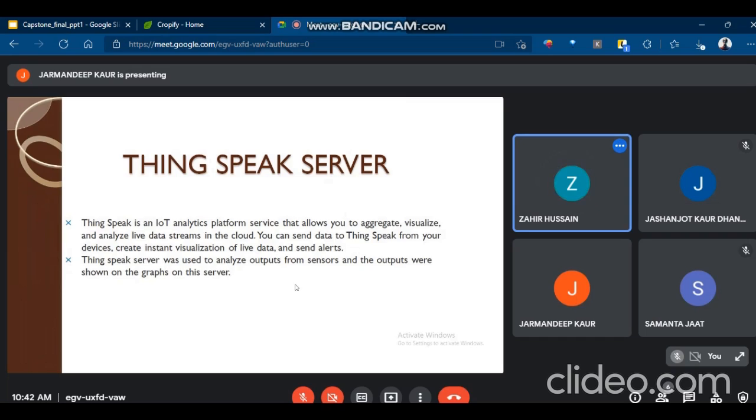Basically, to do this, on our Arduino IDE we go to the board manager settings and click on ESP8266 NodeMCU. After that, we include the necessary libraries. Each ThingSpeak server is provided with a different API key and a channel ID, which we use for reference in our code. It provides us with concise real-time graphs, which are very helpful in analyzing and understanding. From there on, we can present this data on our website.